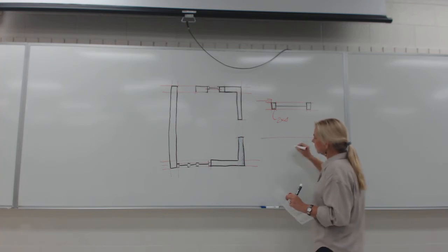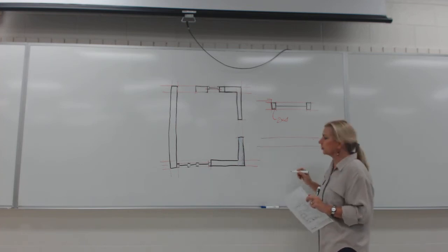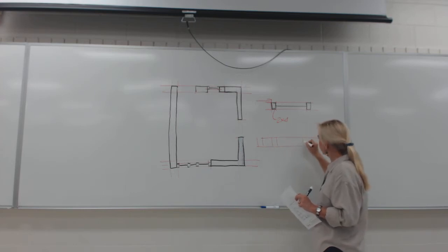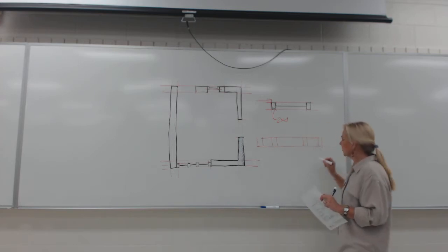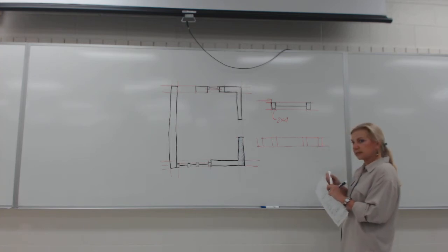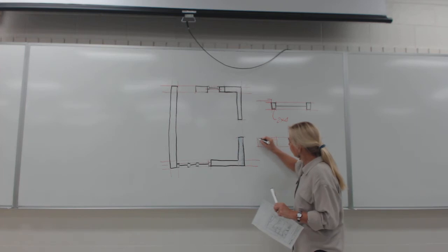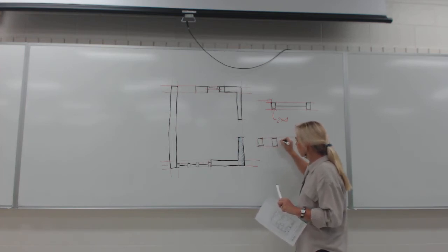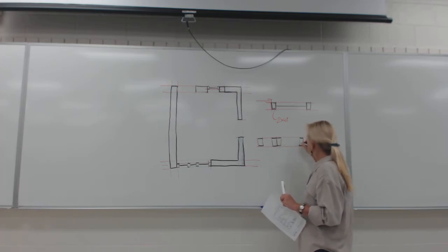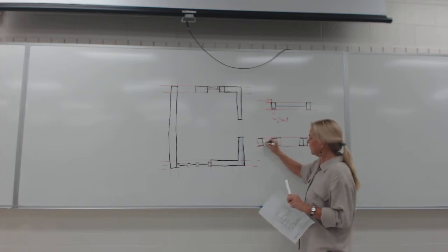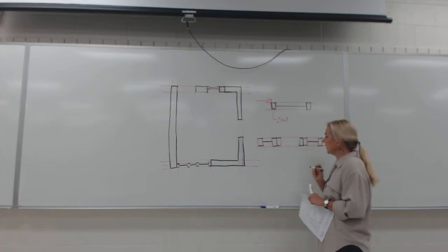So again, the door also, you can draw it the same way, 4 inches. But then we have a frame, and I think 12 inches or so is a side light. So you would have these construction lines, and the construction will be as follows. You have 2x4 frame for the side lights, 2x4 frame for the door. So this looks like a glass that you're cutting through, but the door is slightly different.